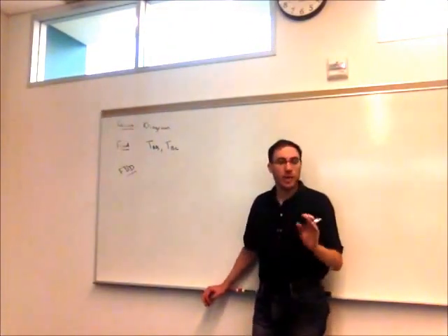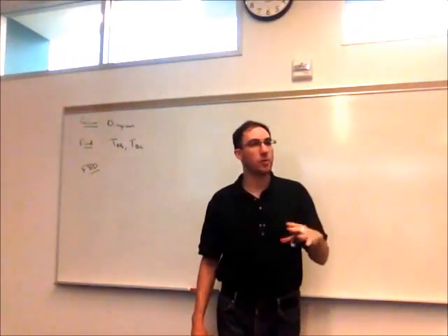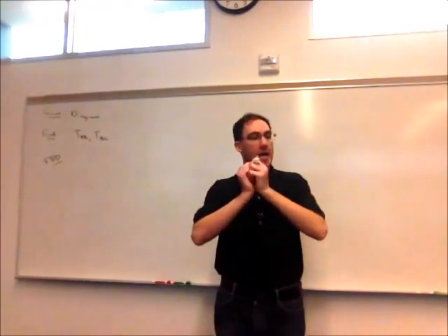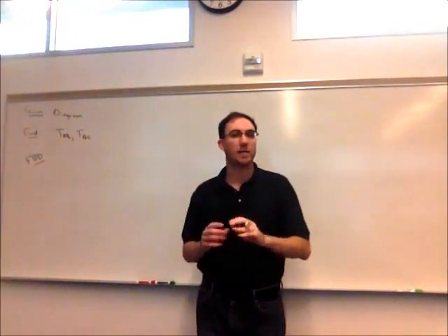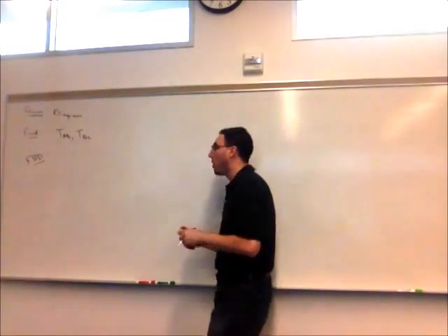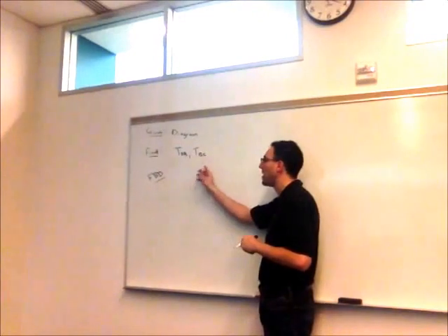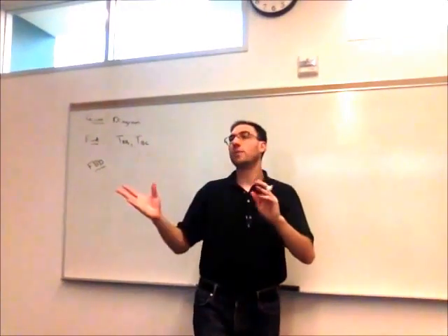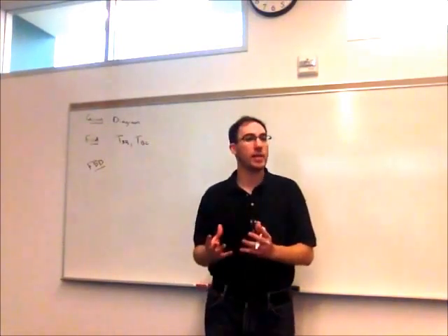So in particle equilibrium, it needs four things. So we have to start with an object, or in this case, a particle of interest. What particle are we taking and isolating from the rest of the system, and then putting all the forces that act on it? So remember, when we pick our particle, we have to remember what we are ultimately looking for, and that will influence the particle that we choose. So this one is fairly obvious, but what particle should we isolate from everything that's attached to?